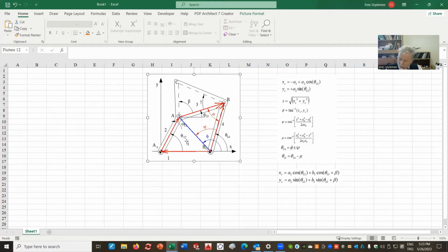That's what we call cross form. This is what we call open form of a 4-bar. Thank God, when the mechanism is assembled in the open form, it will not go to the cross form. When it's assembled in the cross form, it will not go to the open form. So we are safe. You have to take plus or minus once, and that's it.